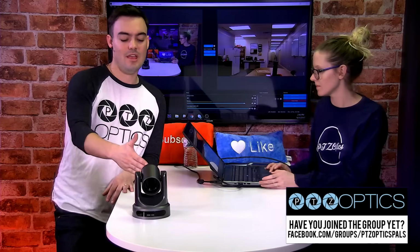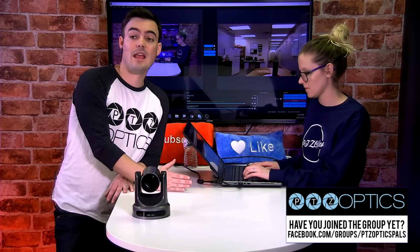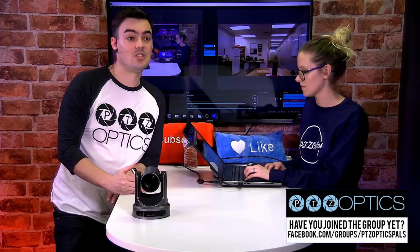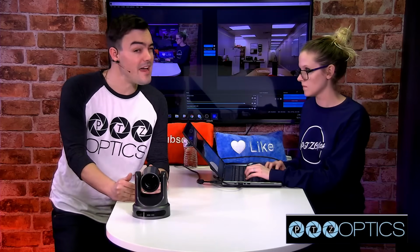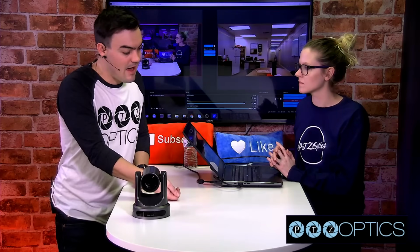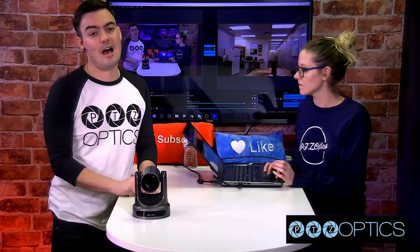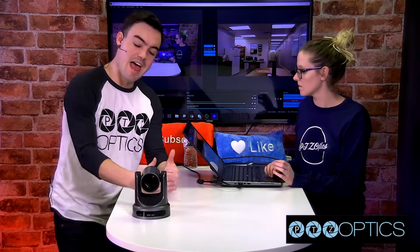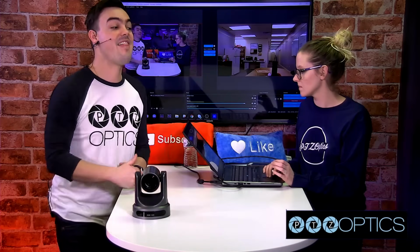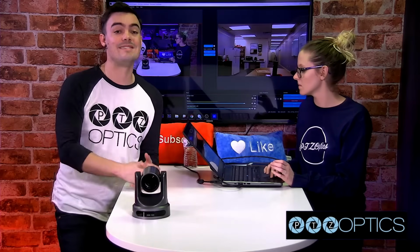So, for example, if you're running the PTZOptics camera into vMix or Wirecast, that's the 60 milliseconds. But then if Wirecast is running into another piece of hardware like a Blackmagic switcher or a distribution amplifier, you plug one HDMI into a distribution amplifier and you get 6 out, that's what's called a DA, and you have 6 displays, sometimes that piece of equipment can also add 100 or 200 milliseconds of latency. And that's when you get into the scenario of having an unwanted